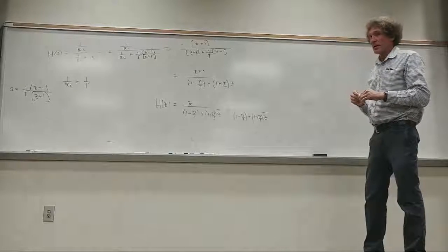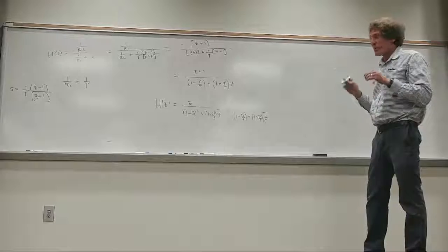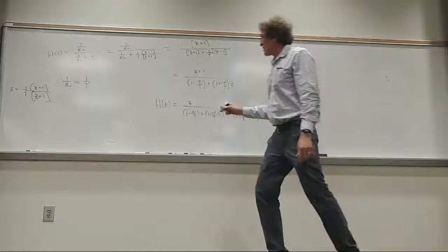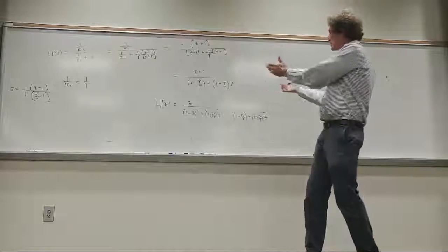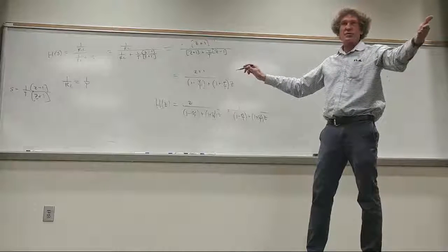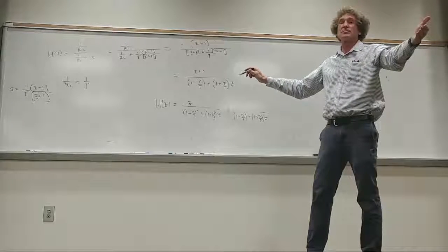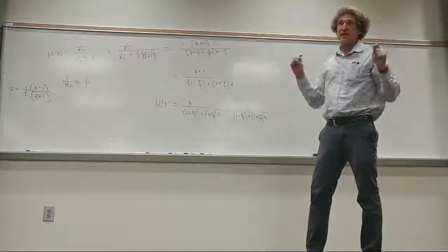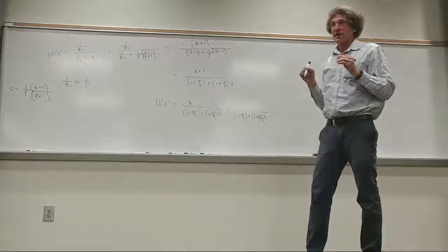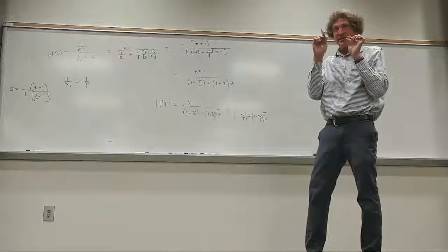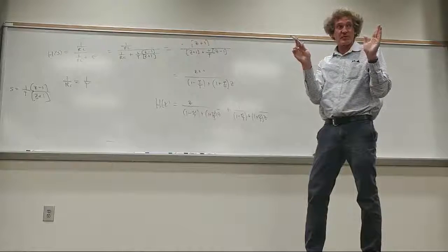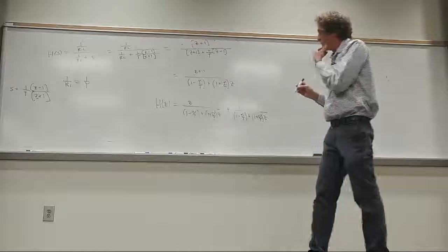Now, remember the whole thing about this is the relationship of z itself. We're building a filter, using this just like we had s to build a filter. When we get the frequency response, we'll replace z by e to the j omega, or j capital omega. Remember z is equal to e to the j omega if rho is 1, and that's if we want the frequency response. But this is right now the filter that we can build.